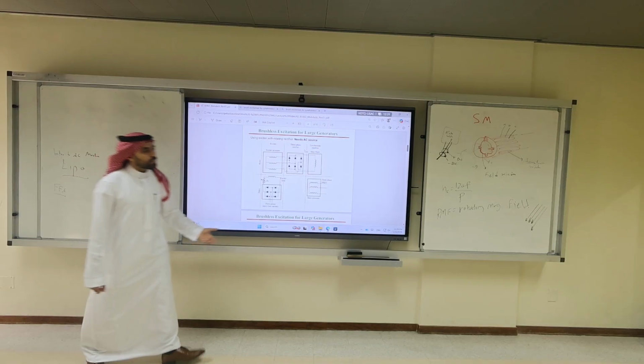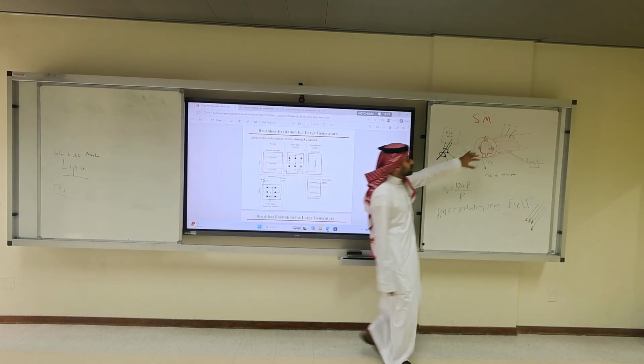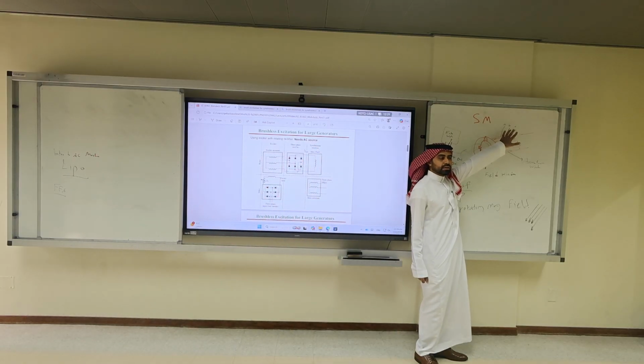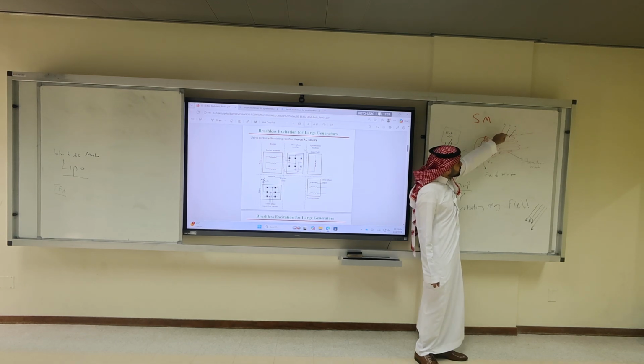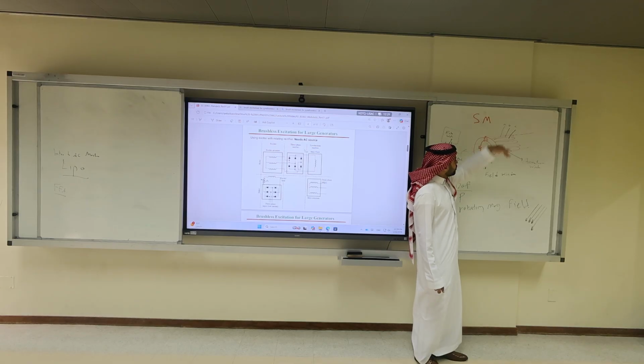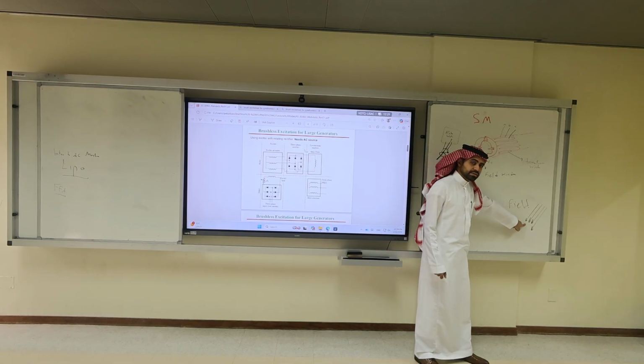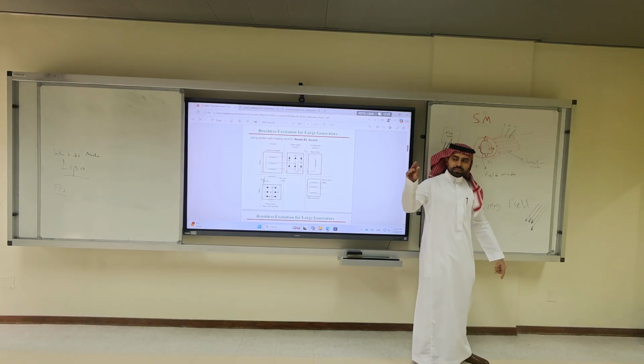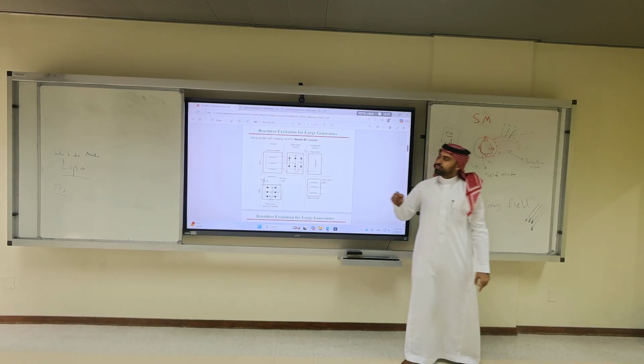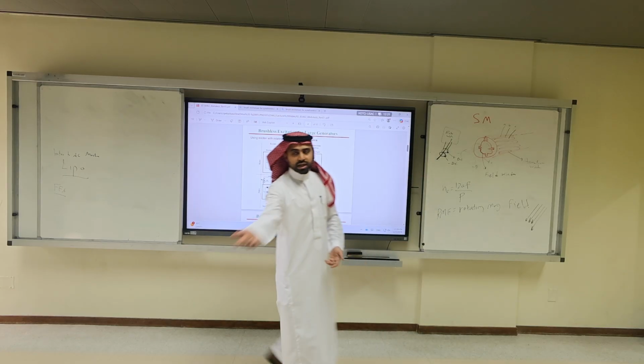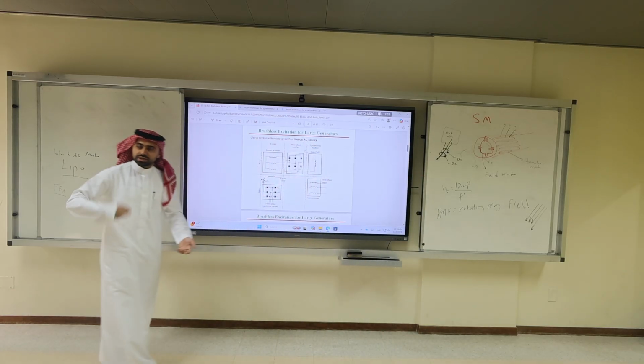What we did is we applied a small AC in some of the windings. Rectified, it becomes what? Small DC. Hook the small DC current in the stator winding. What will happen? We're going to have constant magnetic flux. Start spinning the rotor. If it's a motor, it spins because the car is moving. If it's a generator, because there is a prime mover.